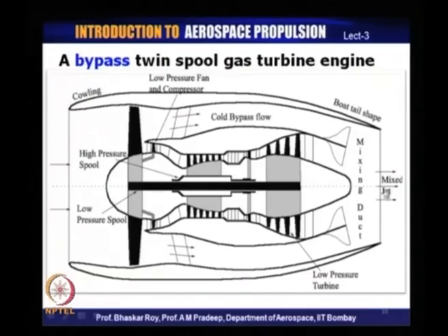because if the pressure profile is not uniform, remember, the thrust that is produced is not going to be a linear thrust in the direction of the jet, but it will be a thrust which will have all kinds of components, sidewise or upwards or downwards components, which will render the aircraft movement in flight in various kinds of directions.